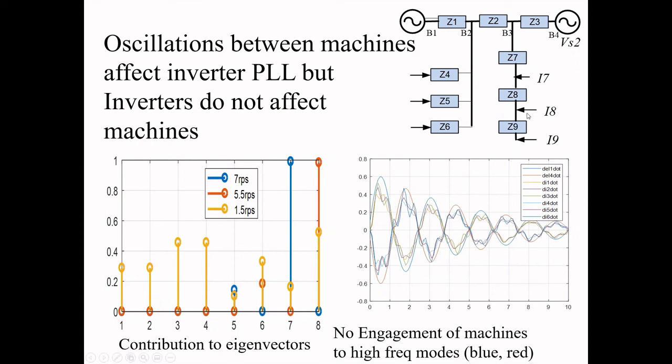So when I'm talking about coming up with a control strategy, instead of inverter 8 trying to do its best to follow the variations of the voltage at its terminals, I'm saying, well, what can we do to have a look upstream and say, let's have a guess of what this voltage is, and then I'll synchronize to that. And that's the essence of what I'm calling line drop compensation. You're familiar with saying, well, I know the current, I know the line impedance, therefore I can infer the voltage elsewhere along my line. And so that line drop compensation concept was the beginning of these control strategies.